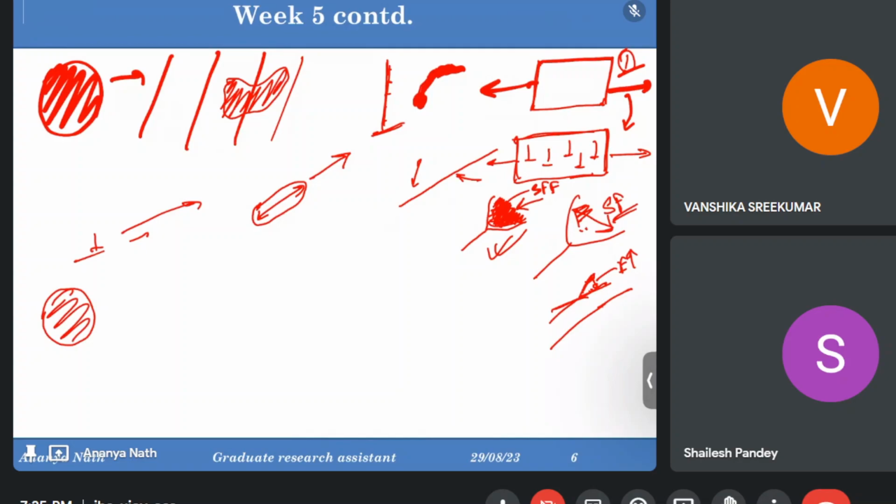And it's easy for the screw piled up dislocations to cross slip because of their Burgers vector. It's not like screw dislocation will always feel easy to move forward. It's easy for the edge to move, but for piled up, it's vice versa because of that Burgers vector thing.